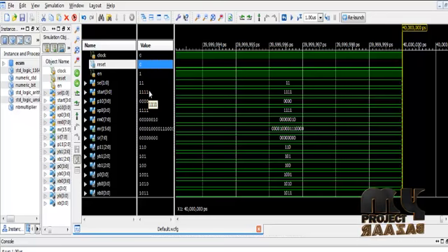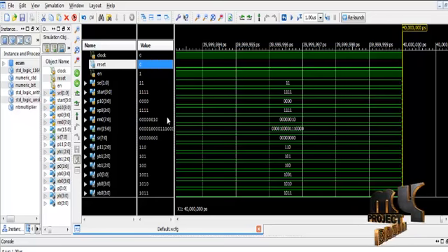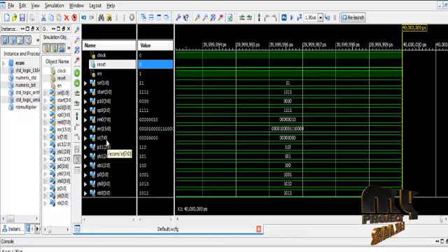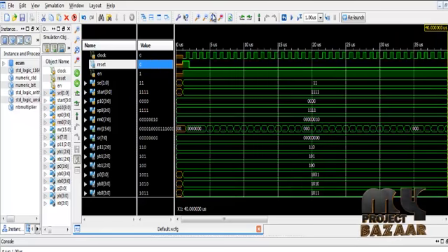That address is given from the finite state machine, and P10, XB0, RM0 are the inputs of the multiplexer in the finite field multiplier accumulator, and MR is the output from the multiplier accumulator, and SR is the finite field squarer output. Then the corresponding output is displayed here, and this is one part of the output. Another part of the output is the utilization of devices, timing and also power.